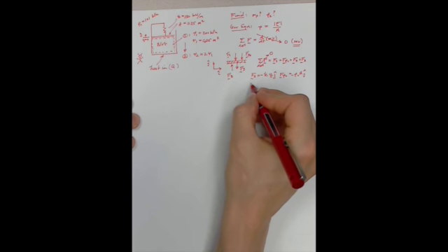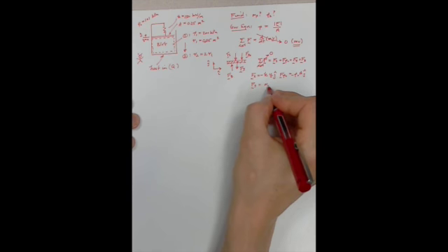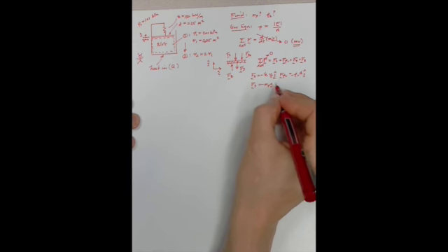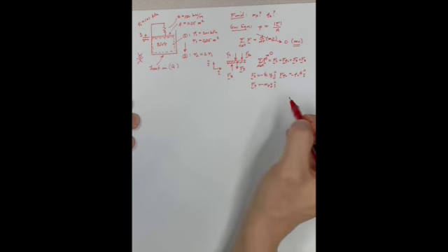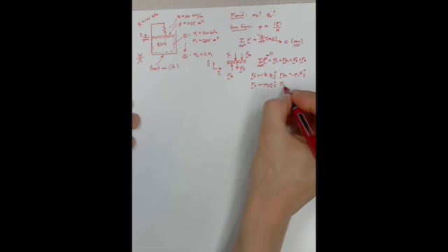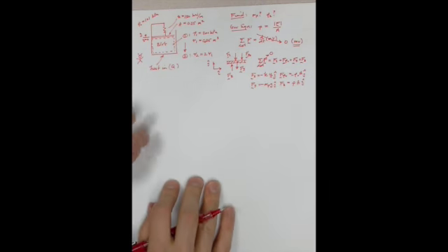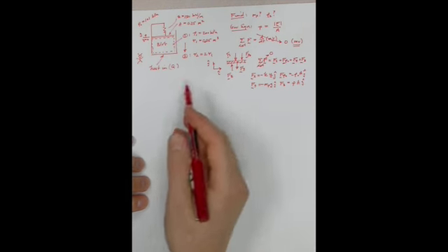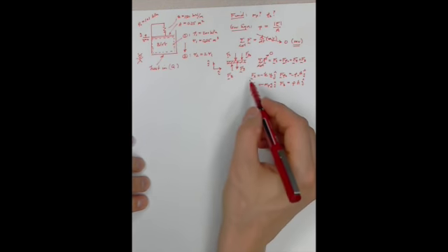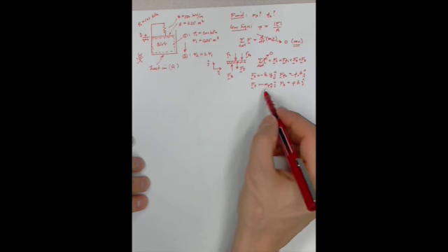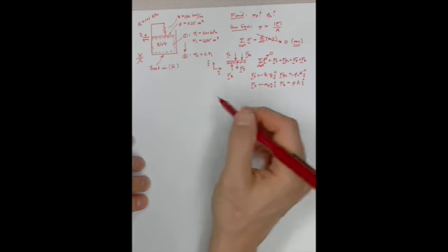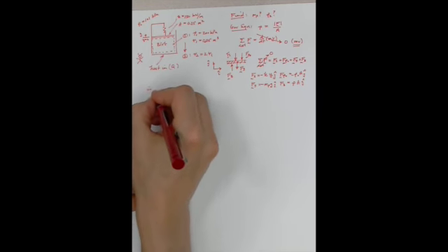I'm going to have the force due to gravity. That would be the mass of the piston times gravity in the minus j hat direction, down. And lastly, the force due to blob is just his pressure times the area that he's pushing on in the j hat direction. So this is the setup that I've got. Let's plug in these constitutive equations into my force balance, and I get in the j hat direction